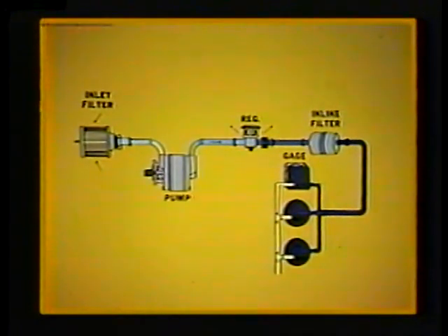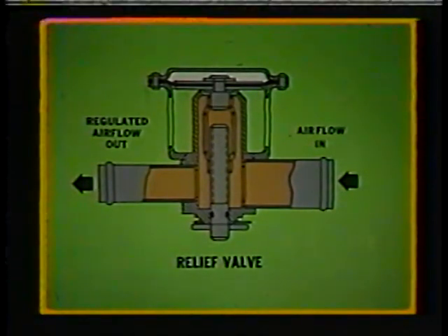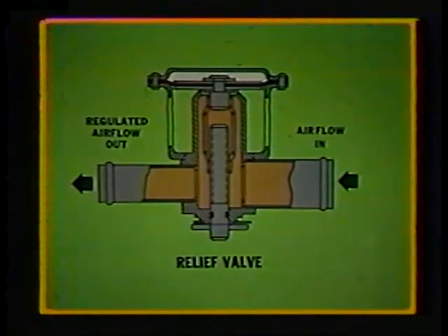In a positive pressure system, the relief valve is located on the pump's discharge side. This maintains the proper pressure required by the instruments or other appliances. In this type of installation, air pressure from the pump acts on a preset diaphragm, opposing the force of an adjustable spring. Excess pressure beyond the regulated limits lifts the diaphragm and dumps it overboard.